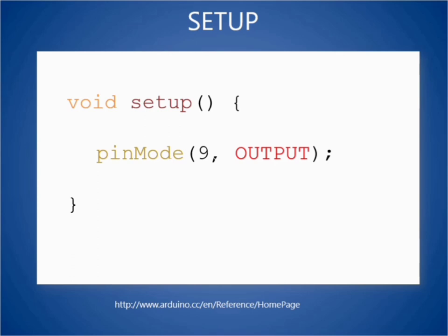So this is the first void setup function, and under this you can see that we are using pinMode, and this is how it is written. You can call it the syntax for writing pinMode. You have to be very careful that this Arduino IDE is case sensitive. You can see here pinMode is written a little bit differently.